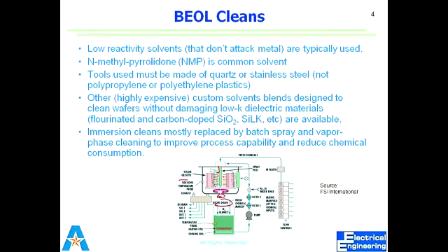Okay, so there are actually two steps of the cleaning process. One is named FEOL, that is front end of line cleaning, and the other is named back end of line cleaning, BEOL. As the name illustrates to a certain extent, front end of line means starting from the silicon wafer to the process where the first metallic deposition comes into account.